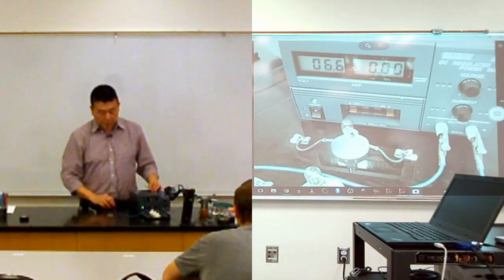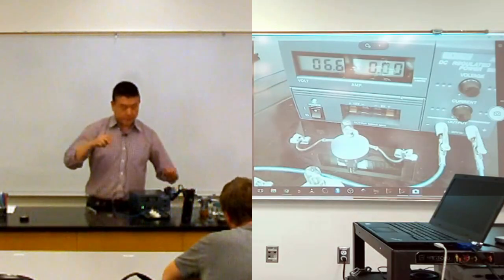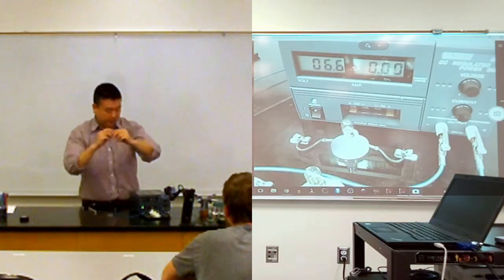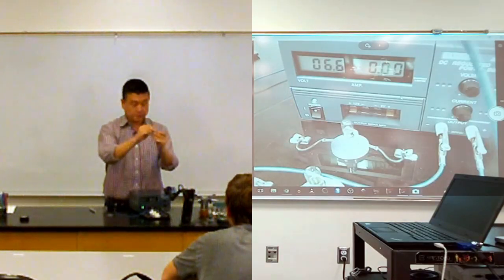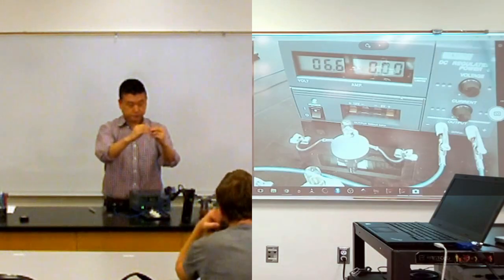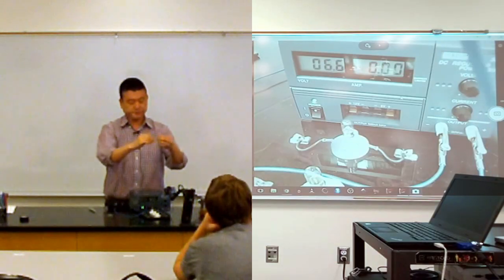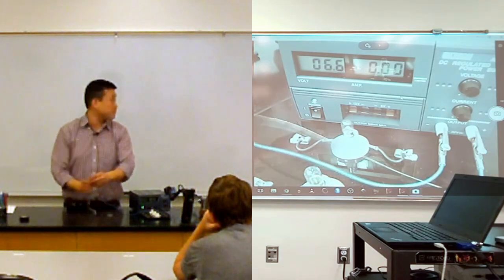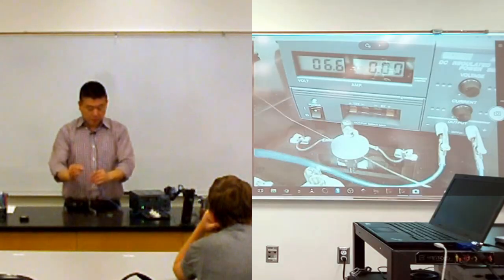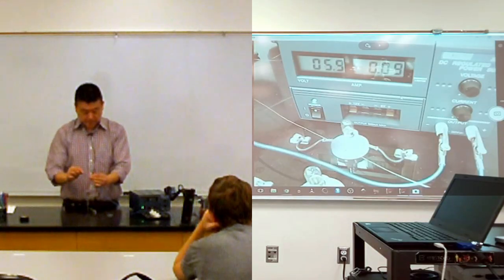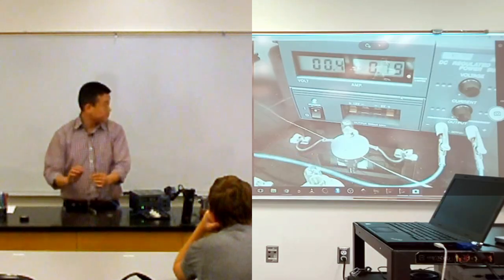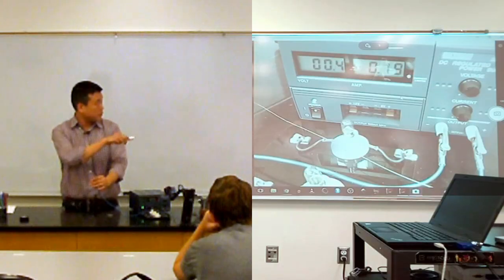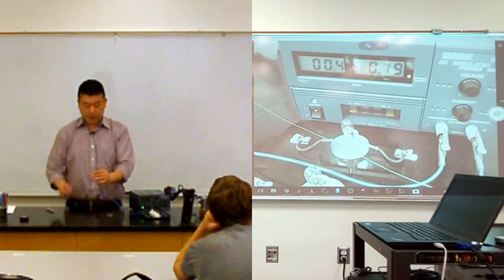But when you set up a particular arrangement, sometimes you don't see 0 volts between 2 ends of a conductor. So let me connect one of the wires to this end here. Wire connected here. Now let me wrap it around for good measure. Right now the other end is not connected, so it's reading 6 volts as you might expect. But when I connect this at this end here, oops. Now it doesn't quite read 0 volts anymore. It's reading 0.4 volts.